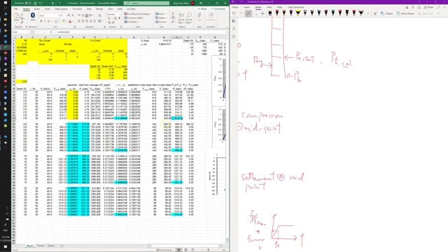And at the end of the day, the one that you assume and the one you calculate are within a tolerance that's smaller than a certain number. So a certain threshold, and the threshold usually depends on the spec, or depends on how close you want to get. But something like less than 0.05 kips, or maybe 0.1 kips is reasonable. So we stop here. So at the end of the day, you see the one that you assume and the one you calculate are very close to each other. So you finish this segment.